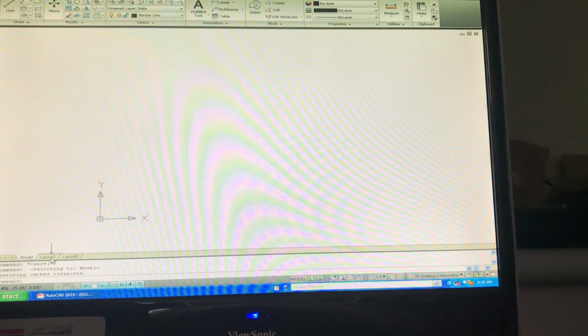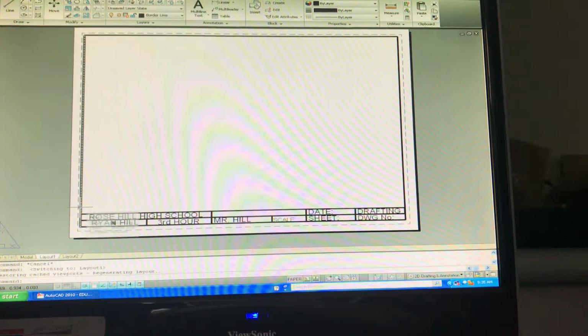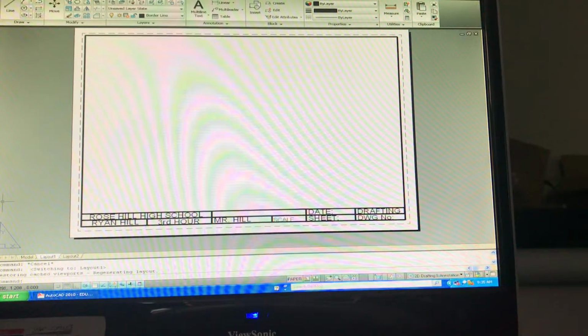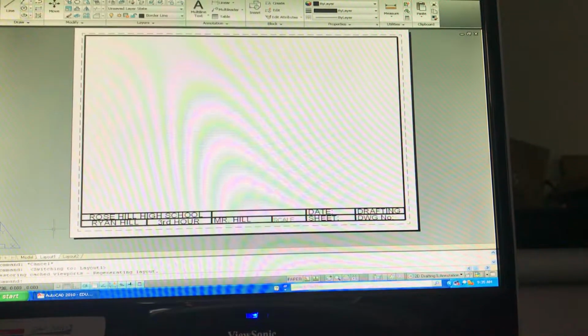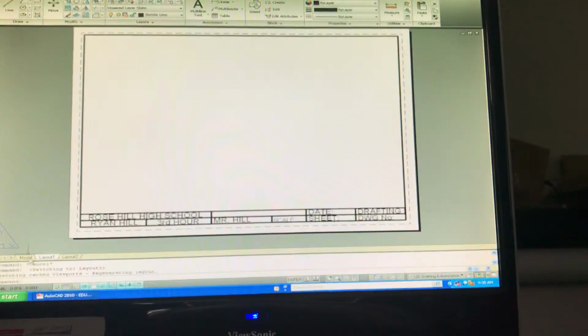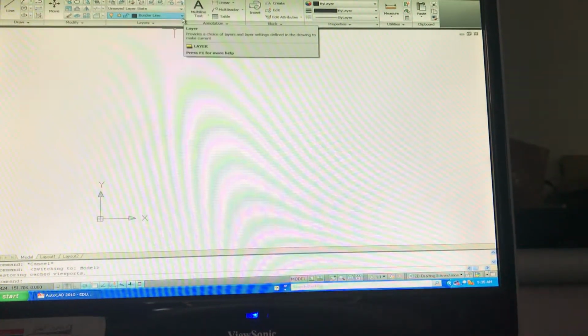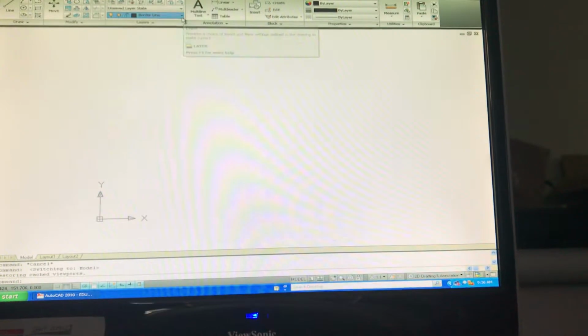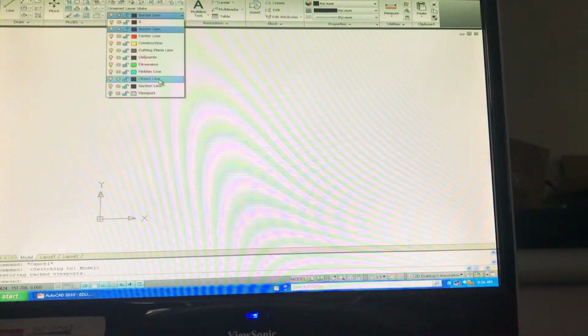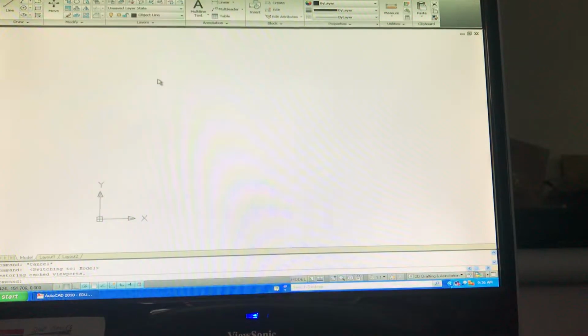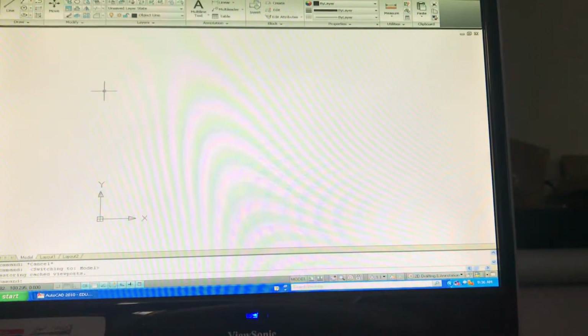You notice that border line selected because, well, all these are border lines. Your title block is drawn in border lines. So how we start creating a drawing is we follow the same steps that we did by hand. We're going to start in our object line layer because what do we start with? We start with our front view, which is drawn in object line. Okay, we're going to go back and do the half lap that we drew up here.